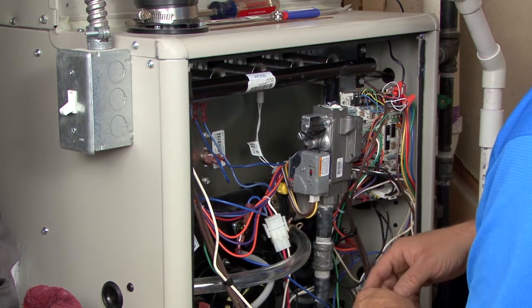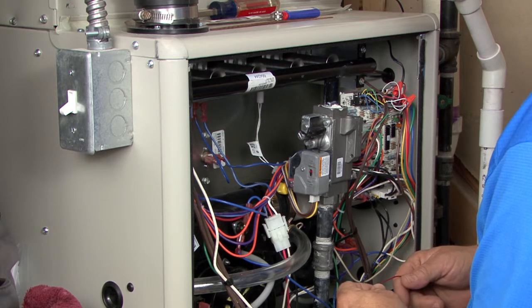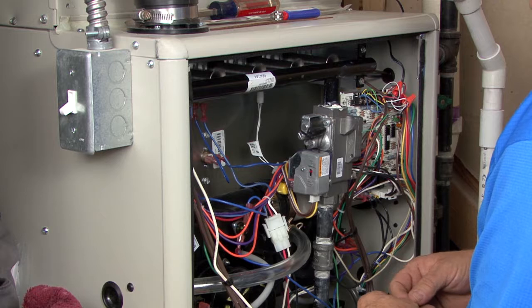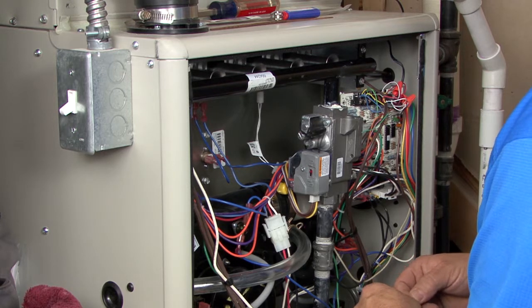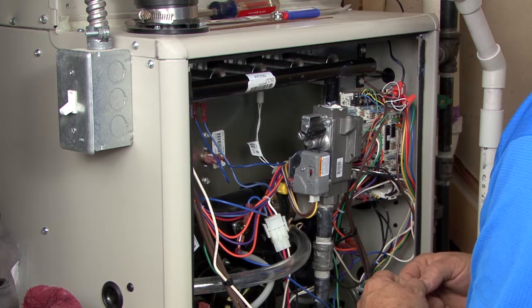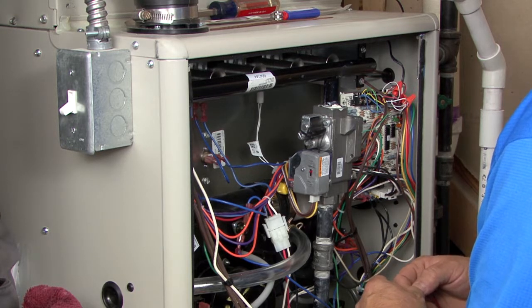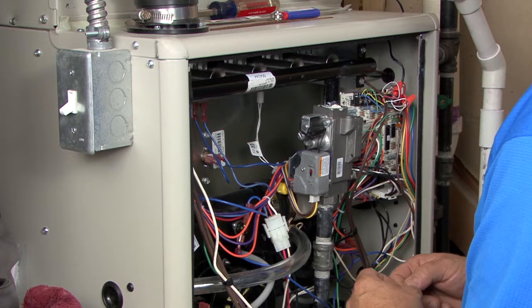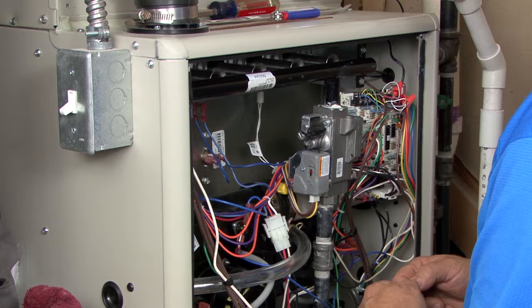So, Greg, it really sounds like there is kind of an in-depth process here in terms of performing an effective and thorough smoke test on a heat exchanger. You certainly hit on a few steps beyond just calling for heat and shutting the gas off and waiting for the blower to turn on. It definitely sounds like just calling for G is not enough, because that doesn't guarantee that we're going to have a high enough blower speed. So when guys are performing a smoke test out in the field, they're going to want to walk themselves through that process to make sure that they're performing it as accurately as possible, and they're not setting themselves up for results that are less than definitive, and then they're just right back where they started.